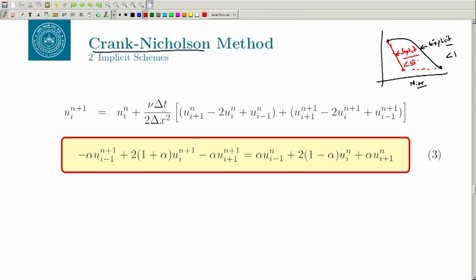Okay. So, similar to the implicit approach that we had in time, you can also have a scheme called the Crank-Nicolson scheme. So, what it does in this Crank-Nicolson scheme, you basically take the average of the nth time step. So, this is my nth time step and this is my n plus 1 time step, right. So, we will take the average of these two things on the right hand side. So, you can see it here. What we have done, we have taken 1 by 2 of values at the nth time step, and then half of the n plus 1 time step.